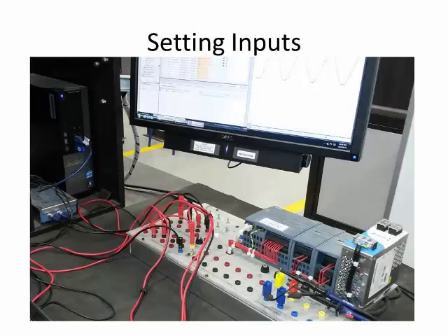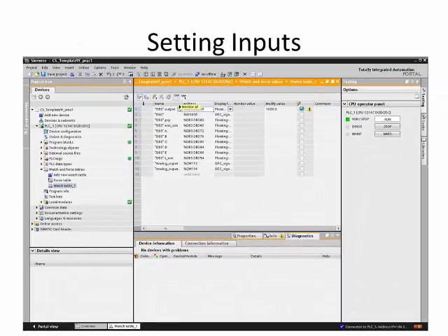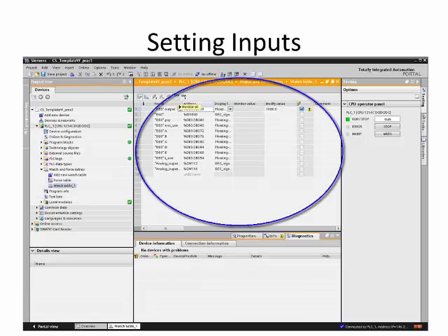The program also displays the values of variables within the PLC during operation and allows us to make changes to parameters to which the PLC will then react. The display of variable and parameter values is done via a watch table in the TIA Portal. The watch table can be opened from the project tree window on the left-hand side. The watch table displays a list of all the system variables and parameters. These values can be modified from this table.